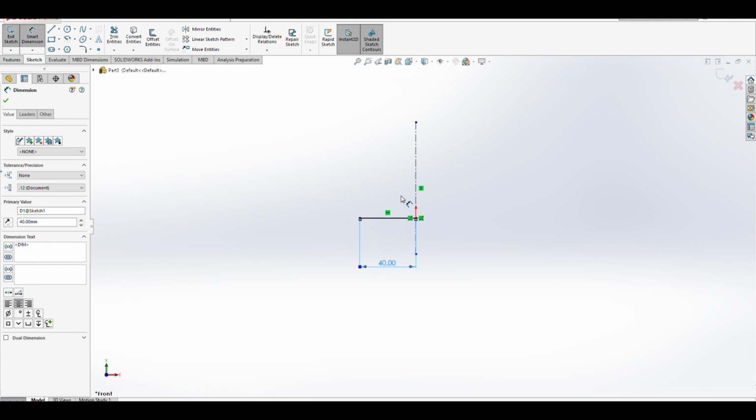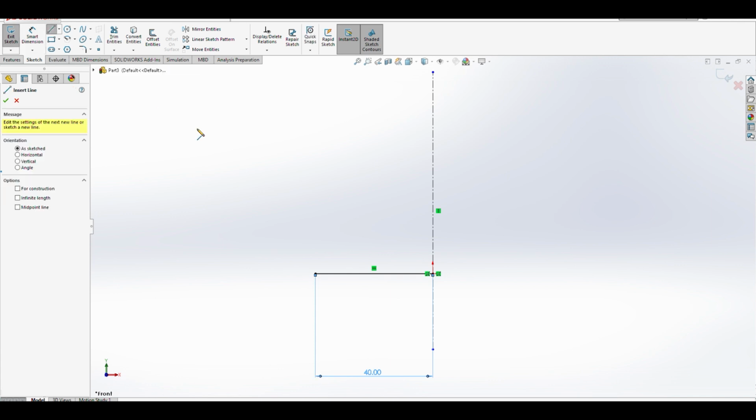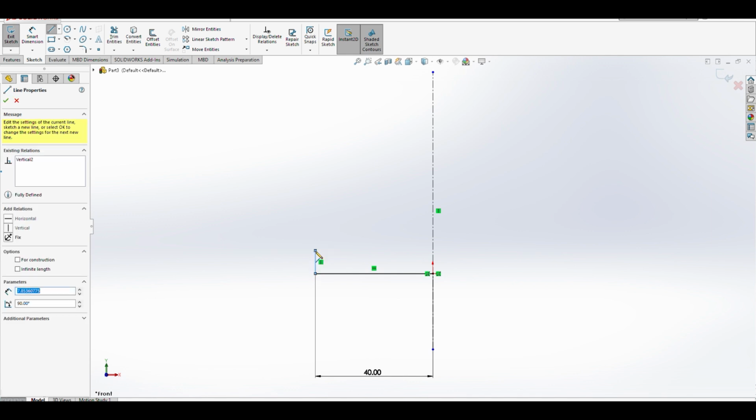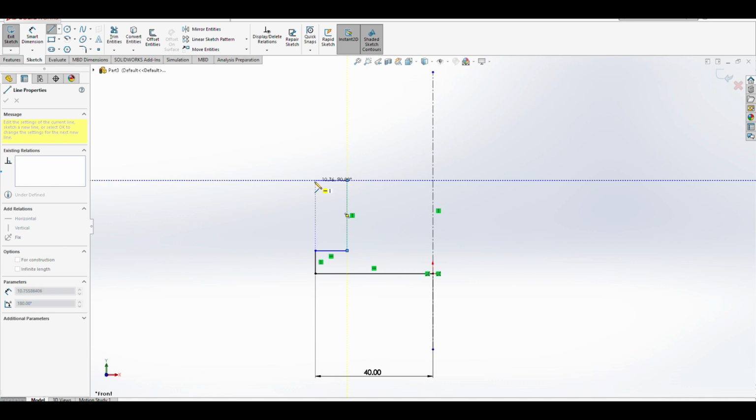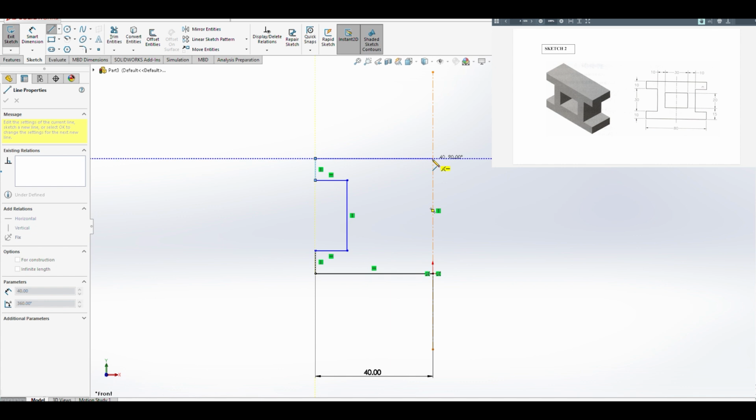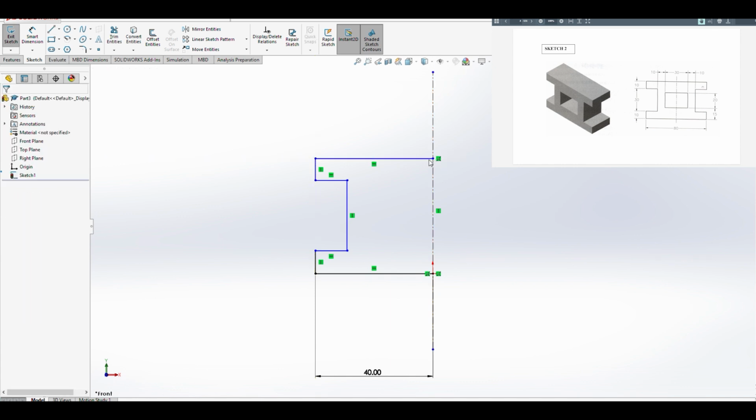Now it's important to get that first line in with a dimension because all the other lines are sort of connected to that first line, and we can sort of gauge how big the rest of our lines are going to be based on that. So I'm going to go ahead and draw this tab that comes up, and this drawing sort of comes in a little bit like this, and I think this line goes straight up, and I'm going to wait for this little leader line to kind of come across and connect with this point, and I'm going to push that across just like that. Okay, everything's horizontal, everything's vertical. I'm double checking my lines. It's very easy to make a mistake if you rush through that part.